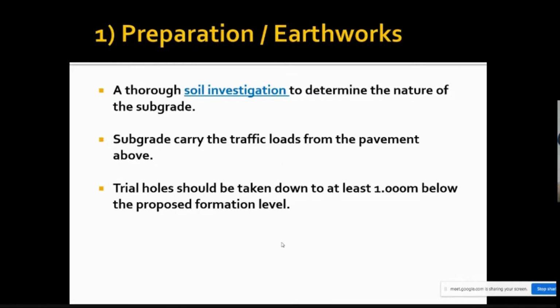If you study buildings, we have two types: one we call load bearing and the other one is structure bearing. Structure bearing means you have columns and beams. The beam transfers load horizontally and then loads go vertically. Then you will have a pile cap, from the pile cap you transfer load to the piling, and from piling you distribute load to the ground.